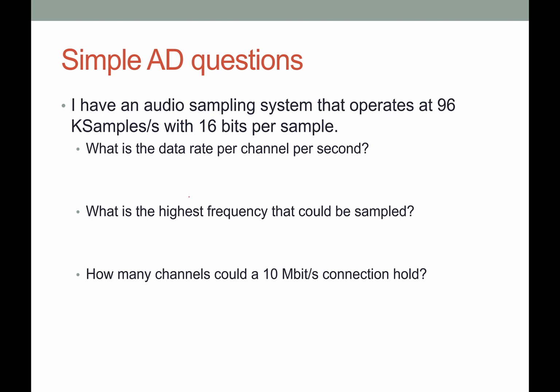What's the data rate per channel? Well, we've got 96,000 samples per second times 16 bits per sample. That gives us the data rate.